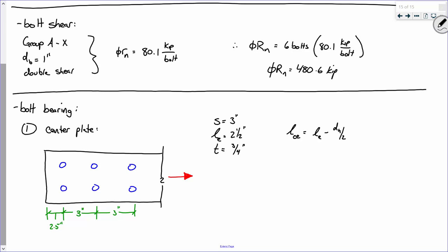So the edge distance, that's 2.5 inches, minus 1/2 of the hole diameter, which we did up here, and we got 1.0625. Tell me what you get here, and we'll just say 3 decimal places. 1.438. Anybody second that? You got voted down. 1.969. Was it the half? That's no big deal. No biggie. All right.